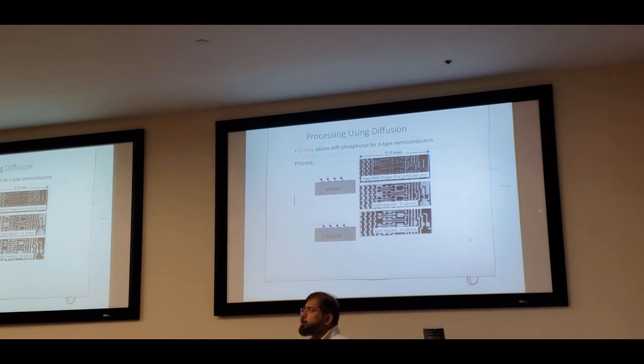So, why is it important? The conductivity depends on the number of dopants you have in silicon. So it must be very precisely controlled. The dopant concentration should be precisely controlled to get certain properties of that semiconductor, which is also important. And you can see that ICs are everywhere, right? Integrated circuits and semiconductors are everywhere. So you need to have a very precise concentration.